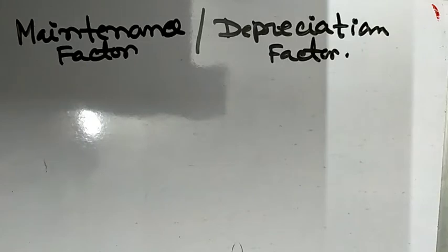The conditions in the majority of industries are dusty. Unless there is a regular lamp and lamp fitting cleaning schedule, there is bound to be depreciation in the light output due to deposition of dust and soot as a dark film on the light source. Deposition of dust and soot on the lamp is technically called soiling of the lamp, and depreciation of light in addition to the soiling of the lamp may be due to the soiling of lamp fittings and other reflecting surfaces such as ceiling and walls.